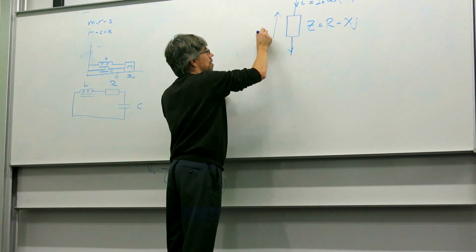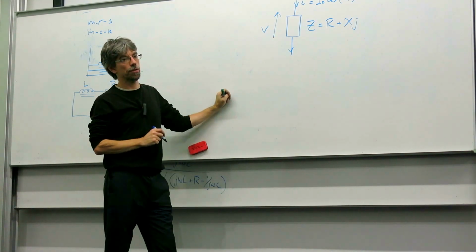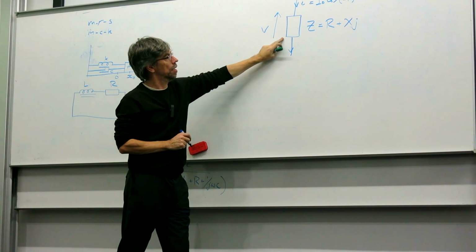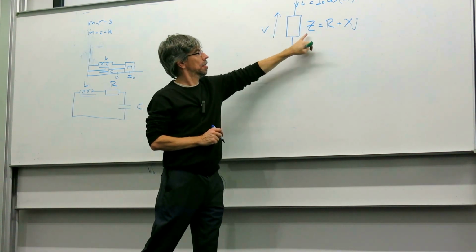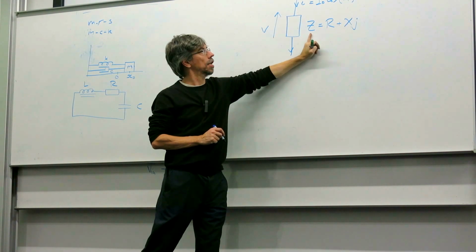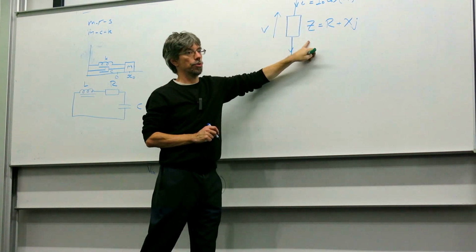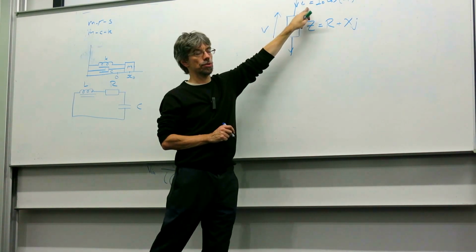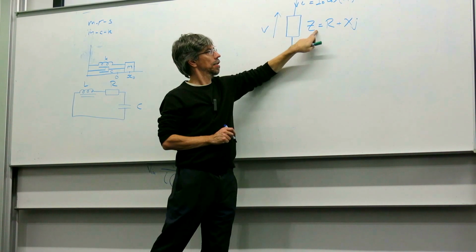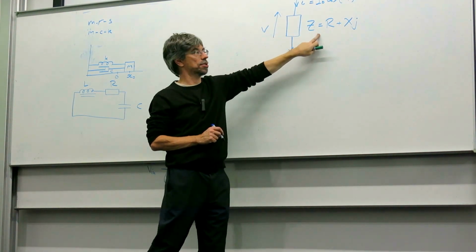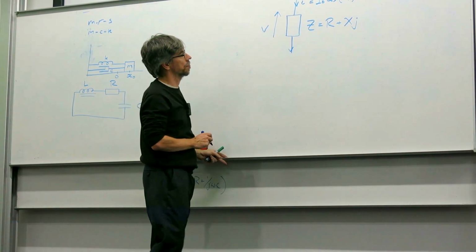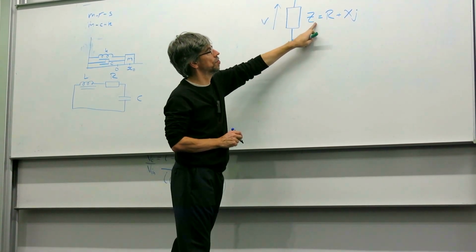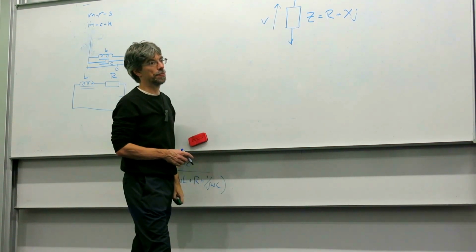A voltage will appear across this impedance. The impedance itself, as long as this is sinusoidal, will cause potentially a phase shift, and the voltage will be scaled relative to the current, accordingly by that impedance as well. So the way we find out how much it's phase shifted and how its amplitude is scaled is in phasor space.